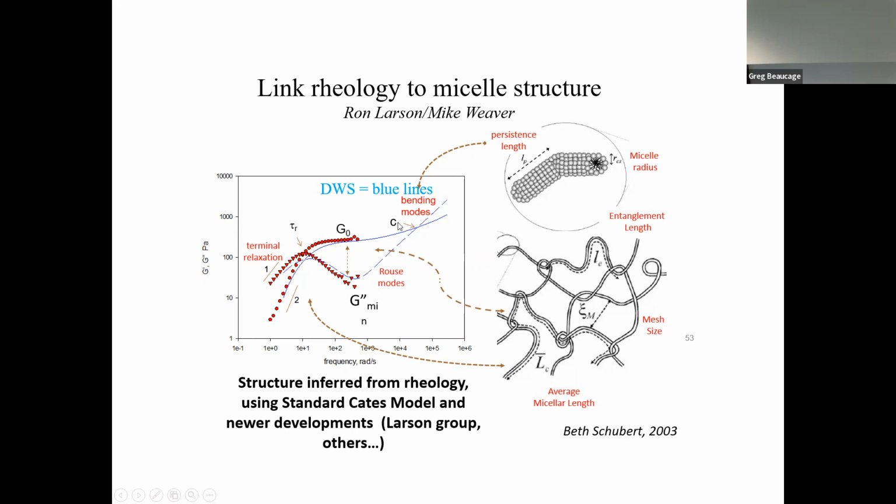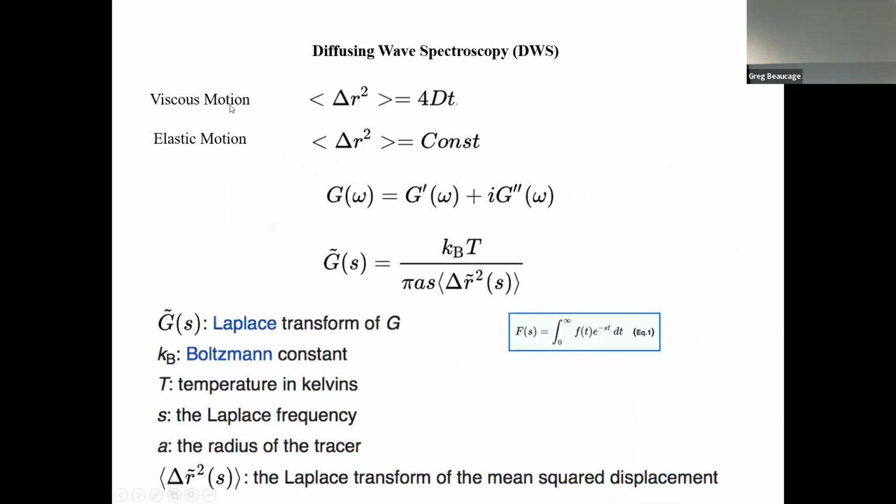One way, in the old days, they had a magnetic ball that you would put in, and you could spin the ball within the fluid, right? So the ball was like a probe. You can use Stokes' law on a ball and figure out the drag coefficient, and from that you can get the viscosity, right? So you have the ball in the fluid, it's spinning with a magnetic field, and you can figure out by how fast it spins what the viscosity of the fluid is, and from that you can translate it into the storage and loss modulus, and you can get to higher frequency that way. So this guy at Penn, I forget his name, I think it's Weiss or something.